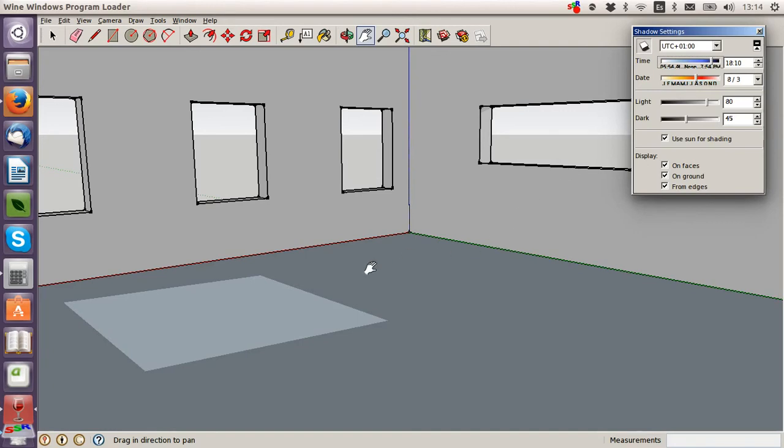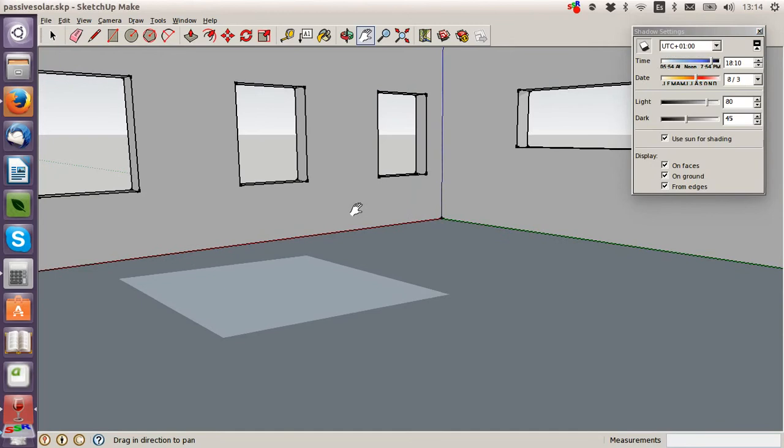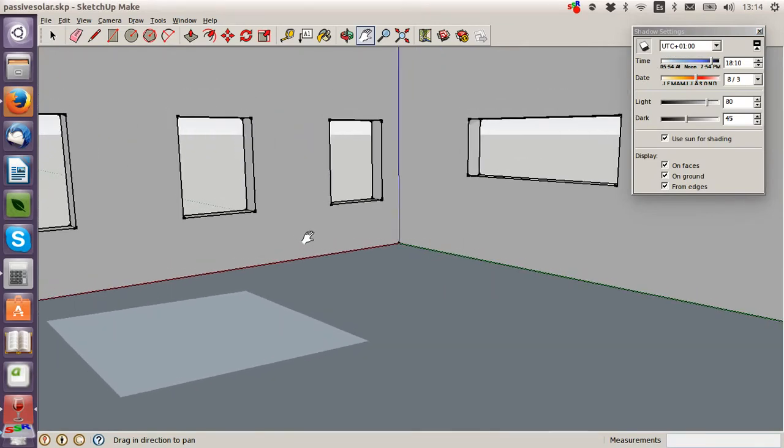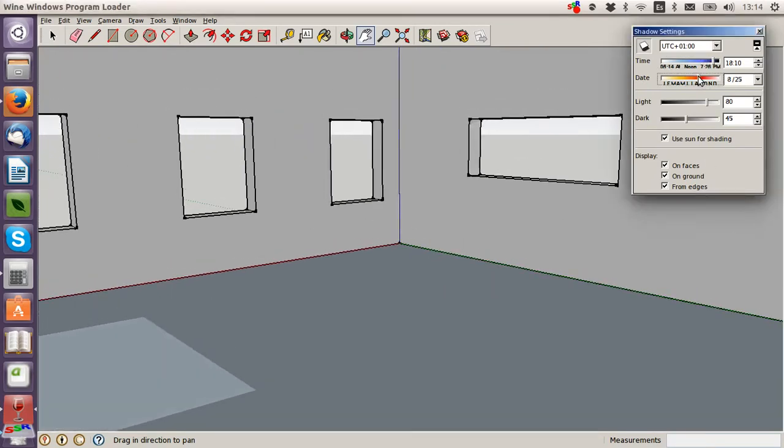In a climate like the Mediterranean, you can have some glazing on the north. It's not a problem. It's not too cold, and you can get something like triple glazed windows, and that would work well in a Mediterranean climate. It wouldn't let too much cold in the winter. It's not very cold here anyway.